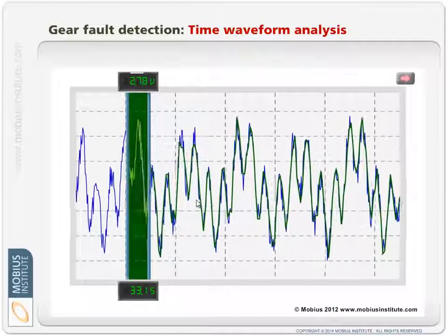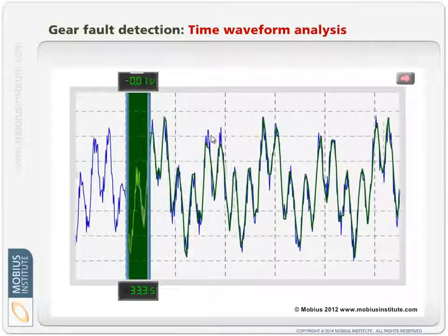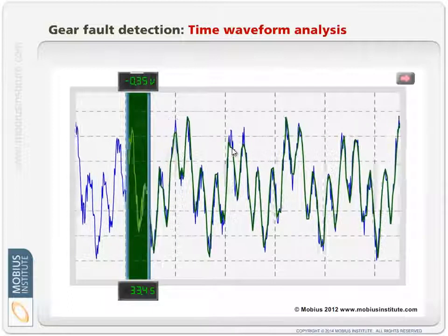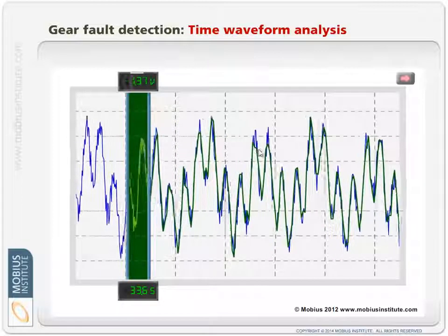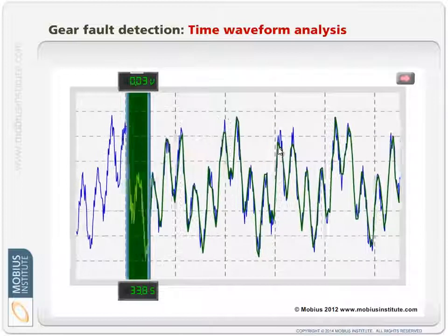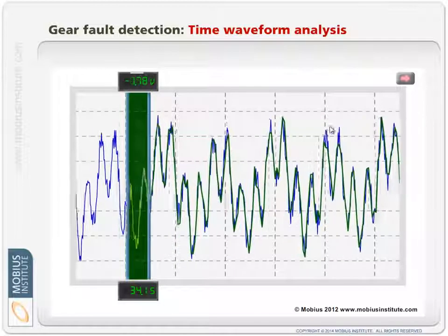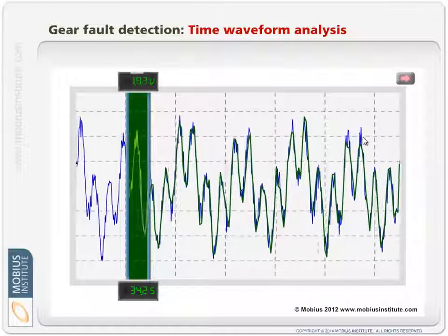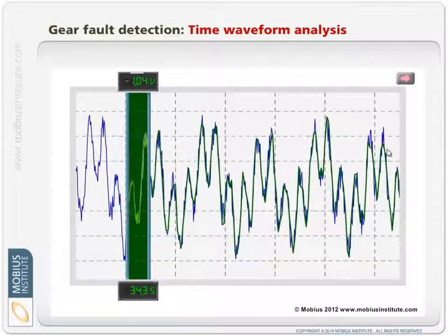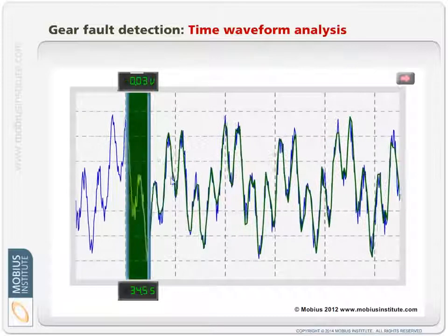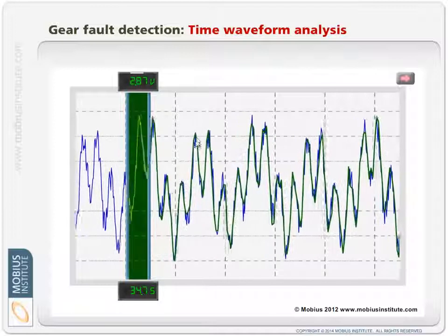I can't illustrate that easily, but if you look here, you'll see just here that there's a blue spike that goes up, but we didn't capture that. The green captured waveform is lower. We ideally wanted to get a digital sample up top here. You can see it there as well. We didn't capture these spikes. We sampled, even now we're sampling too slowly. We might just fluke it.